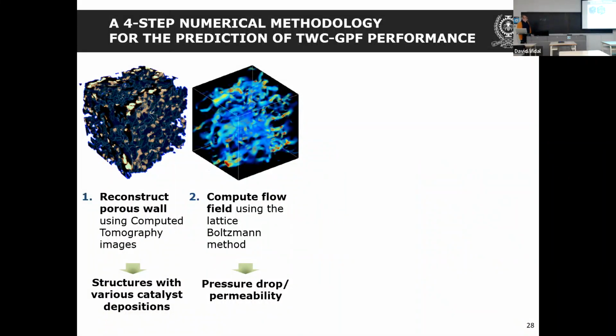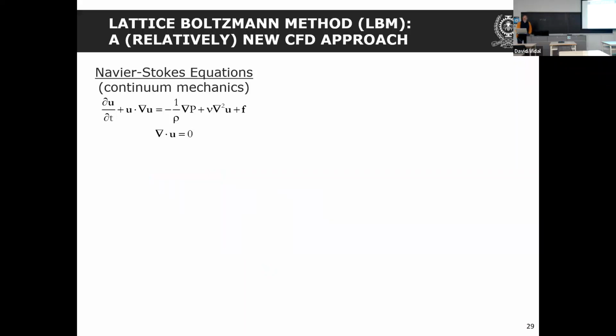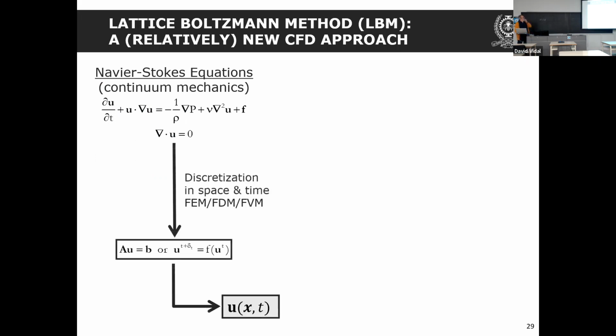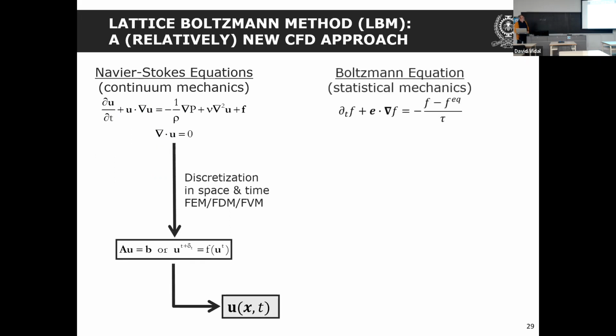Okay. Then eventually, you need to compute the flow field using the lattice-Boltzmann method. So this is one step of the mathematization process. Okay. So lattice-Boltzmann, I won't go into details. I guess most of the people here in this classroom have heard about lattice-Boltzmann, and I taught some class where we talked about lattice-Boltzmann. Just for those of you who are not familiar with lattice-Boltzmann, basically, instead of solving the Navier-Stokes equation, okay, we are actually solving the Boltzmann equation, which is a mesoscopic representation of the gas or fluids.